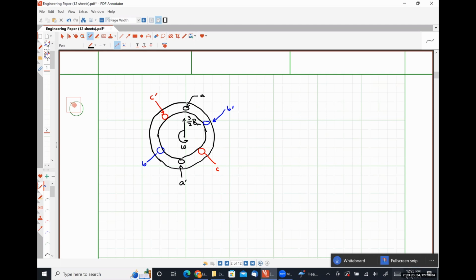Okay, so effectively, all that would happen is that the directions of our B and C phase currents would be opposite, which means we're going to wind up getting rotation in the opposite direction. That's it. It's going to do the exact same thing, except that the rotation is going to occur in a clockwise direction if we swap two of the phases. Everything else will remain exactly the same.